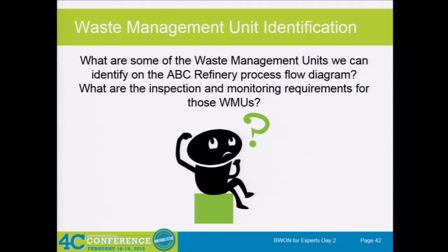Your NPT and CCR sump itself. So this is one, so it's called the sump, but it looks a lot like a tank, and it also looks a lot like an oil water separator, right? So some would look at that and call it an oil water separator, which would require what type of monitoring? The NDE and the quarterly visuals, so both. Then you have your API separator. That's vented to atmosphere, so is there any inspection monitoring requirement for that? No, because it's not controlled.